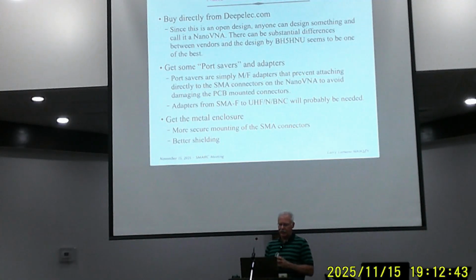You also want to get some port savers. All those are is a little male-female SMA to SMA, male to SMA female. There's only so many insertions with these little connectors before they start wearing out. I mean, they don't have a lot of surface area.